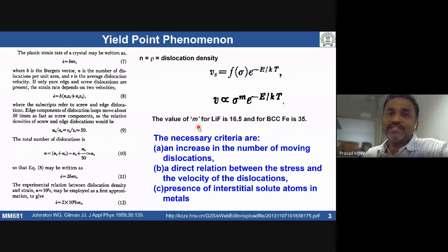So that rough surface is problematic because fatigue property, the resistance to fatigue, is going to be low when you have a surface roughness. At the same time, corrosion property also is going to get affected. So corrosion is going to be higher whenever there is roughness in the surface of the material. So these are the problems we do see with the yield point phenomenon. This is one of the plastic instabilities. Yield point phenomenon is one of the plastic instability kind of phenomena we see in materials, especially in steel, low carbon steel based materials.